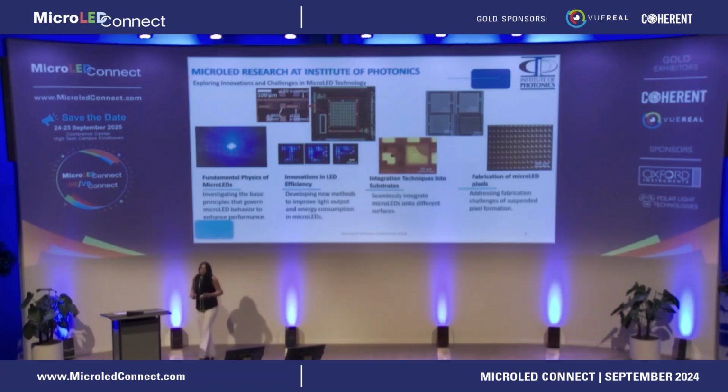For this one, we are talking about individual components that we integrate into actual photonic devices for the purpose of any application. Another part is the fabrication of micro-LED pixels. Because we are talking about integration on different substrates, there is in general a need for your devices to be releasable from the native substrate, in order to pick them up and print them to the target platform that you want. Another part that I'm working on is how we can optimize the geometries, position and shape of the tethers that hold the devices suspended, in order to make the pickup easier.